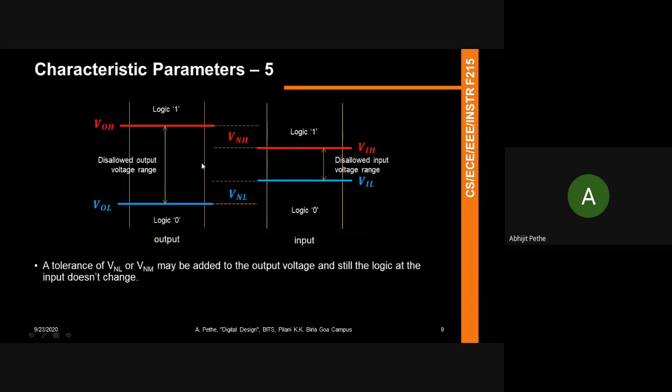For example, a fan out of 10 means that an output of a gate can be fed to a maximum of 10 gates without losing the logical value of that node. Am I clear? So you're saying that the output will lose its power if we give it as input to 11 or 12 gates? Yes. As long as the number is less than 10, when I say the technology has a fan out of 10, I'll be safe. If I have to give it to more than 10 gates, then it'll end up causing an issue. Yes, I got it.